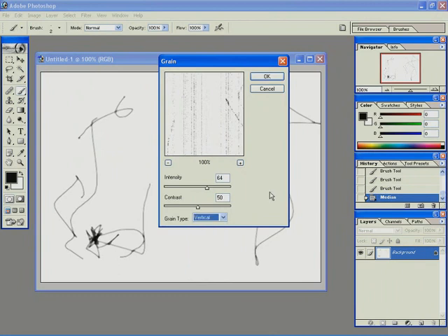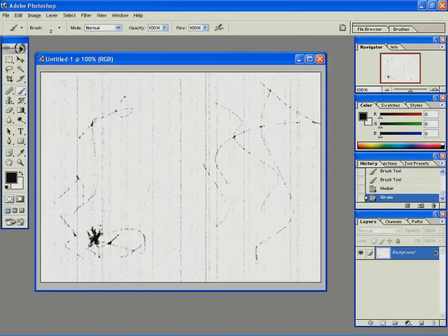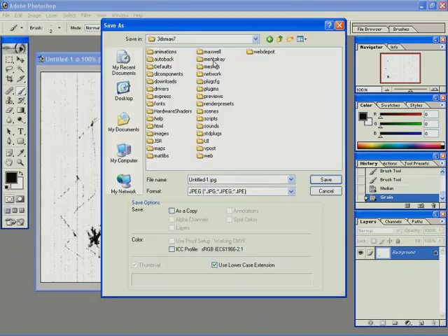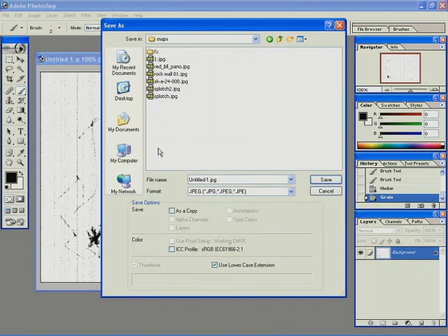So I'll choose File, Save As, inside my Maps folder here. I'll create a folder called Scratches. The reason I'm creating a folder is that I want to use multiple images and not just one image. Now, the requirement is that you should start the naming process with 00x, in this case 001. If you don't do this, Max will not pick up these images as a sequence. So if you just name them 1, it will not work, or scratch 1. So it has to be scratch 001, for example. Now, for simplicity, I'm going to name it 001, and I'll press OK, and this is a JPEG.